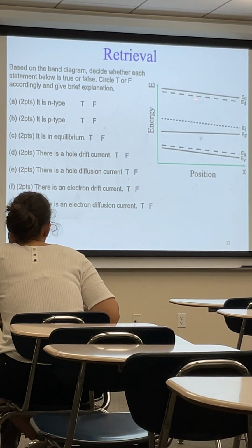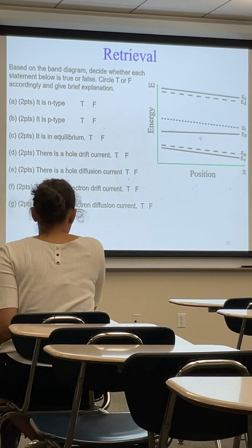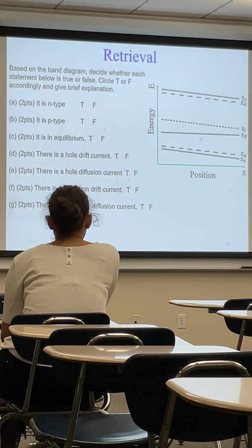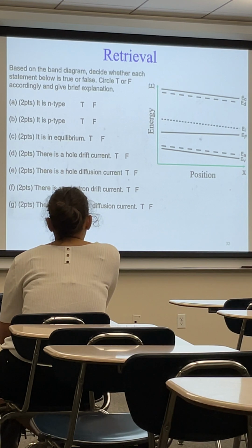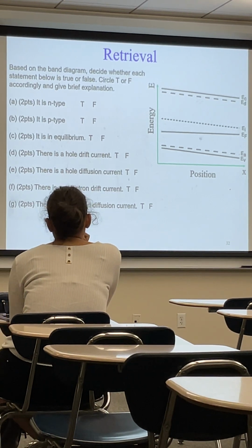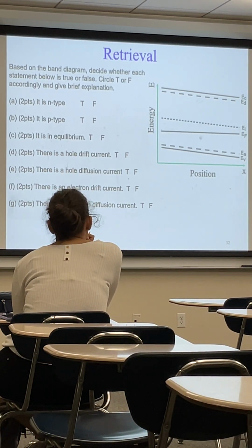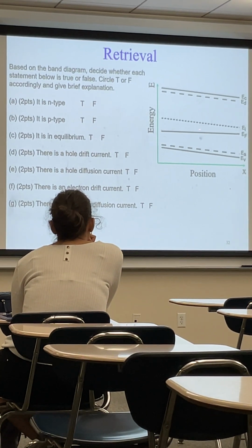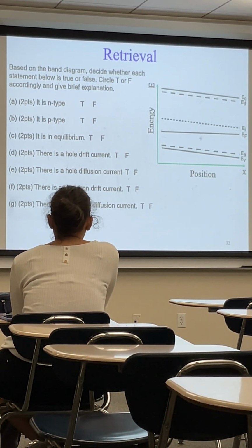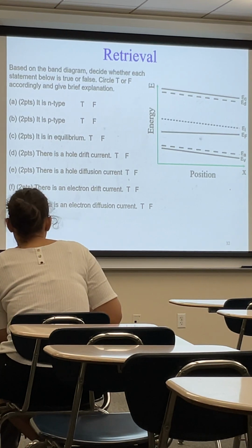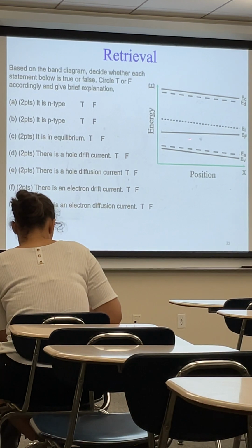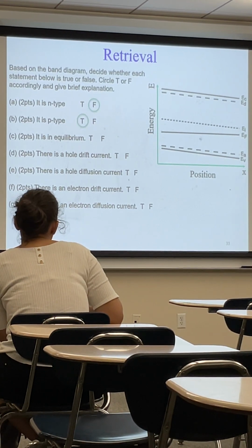So if we have this kind of band diagram, EC, EV, EI, EF, and EA. So is it N-type or P-type? P-type. Why? The Fermi level is underneath the intrinsic level. Yes, exactly. So this will be P-type because the EI is below EF. Okay? Right, good.